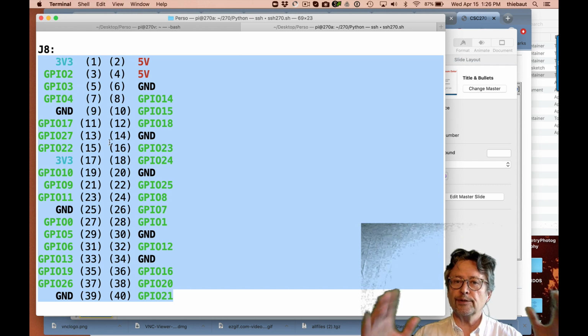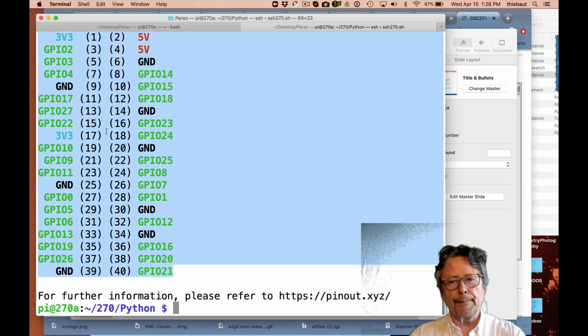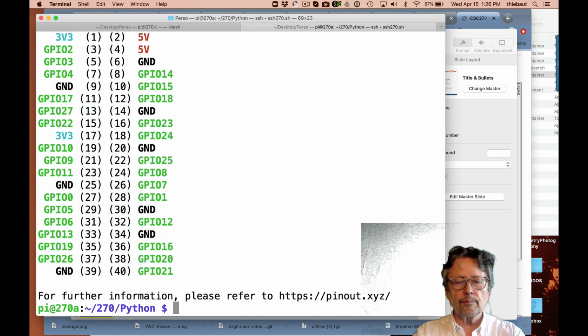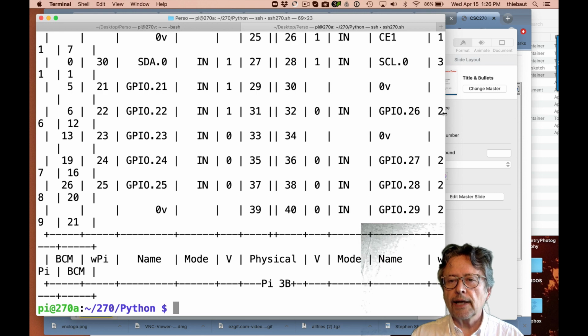It's not as complete as the table that I've just shown previously, but that's a nice way to display it. And then there's another utility called gpio, and gpio by itself is a nice command because it allows us to access pins as input. You can program the Raspberry Pi pins from the command line using gpio, this app. It's kind of quite nice. So you can just at the keyboard turn an LED on and then decide to turn it off without writing a program.